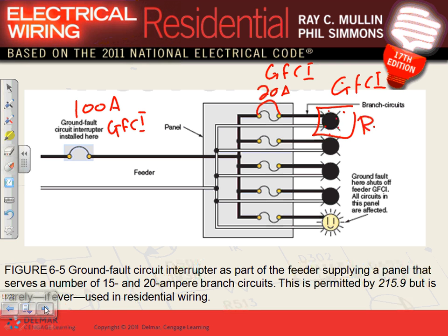Take this. If you put a ground fault protection on the main right here, now what happened? Ground fault protection is looking at 6 milliamps. These are all 6 milliamps in the US. In Jerusalem, these are rated for 30 milliamps. They're higher. Tougher people, I guess. Even with 30 milliamps, guys, if you put them at the main, in the winter, with wiring and things, there's earth leakage to ground. There's a small amount of current that goes in the conduit to ground.